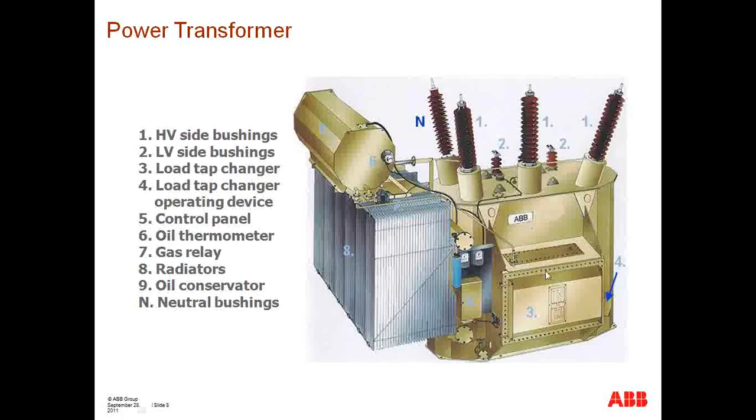Okay, the more current that's going through the transformer, or the more power that's flowing through the transformer, the more losses, and the more RI square losses that are associated with that equation, thus the more energy that's dissipated within the transformer, and that energy is dissipated in the form of thermal energy, which in turn results in a thermal rise inside of the transformer. On that point, you essentially have a balance between the cooling system of the transformer and the power that's flowing through the transformer to keep that thermal rise to a particular level.